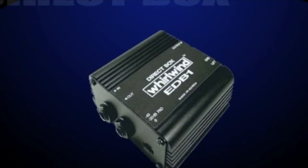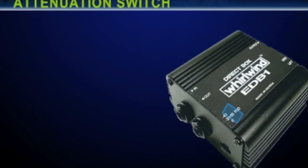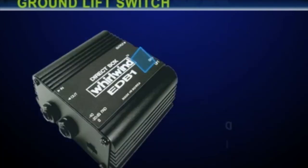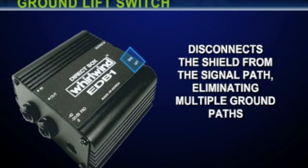Most direct boxes include a ground lift switch to eliminate possible hum and an attenuation switch to reduce the signal level from line level down to microphone level. The ground lift switch disconnects the shield from the signal path, eliminating multiple ground paths.